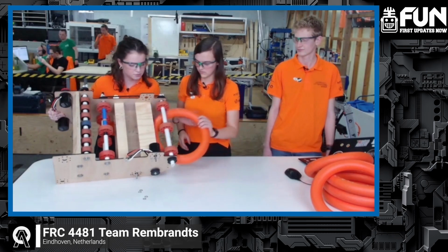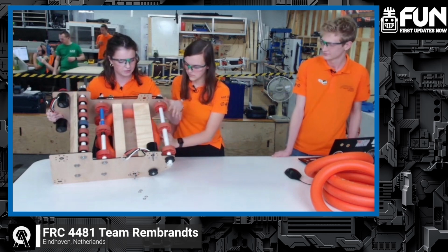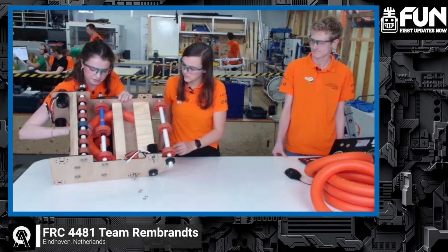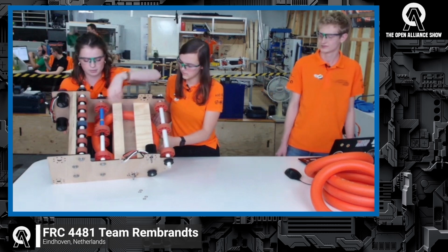The node comes in over here. We have a few feeder wheels over here. Those are compliant wheels, 3-inch, if I say correctly. Yeah, 3-inch compliant wheels. And then we can either score in the shooter by directing it, I will pull it straight this way, so straight on. Or we can adjust the spinning of the wheels, and it will come over here, and then it will score in the amp. So this is actually our second prototype for this, I think.